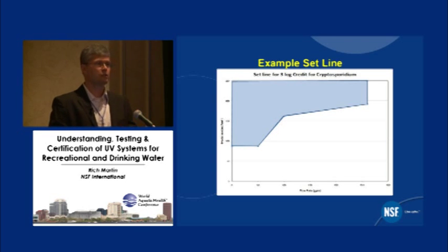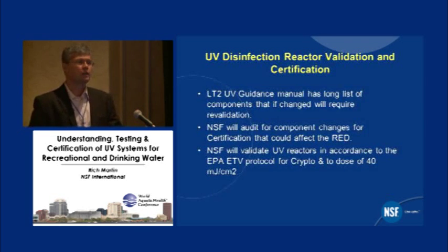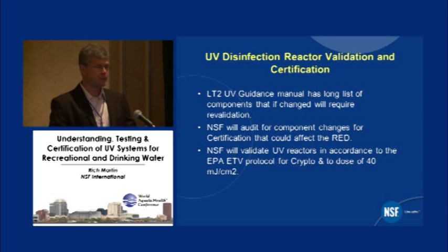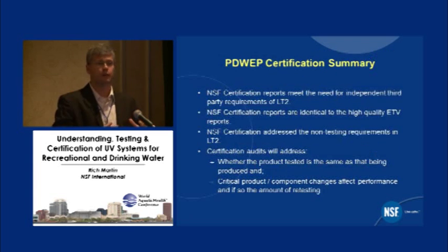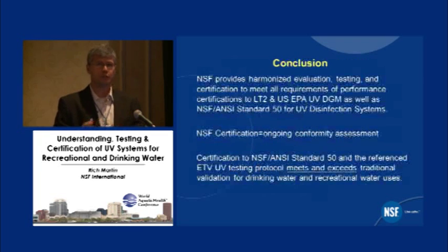It's really this concept of UV transmissivity. Turbidity can be problematic and challenging for light to get through the water and actually get to that organism or material and have an effect. But when we describe the disinfection or kill properties, we use this other term, the UV transmissivity of the water.